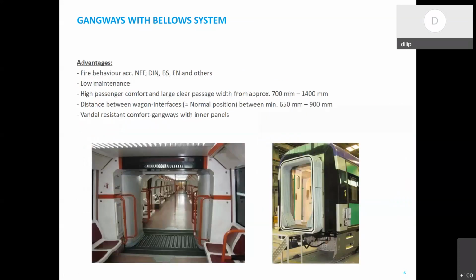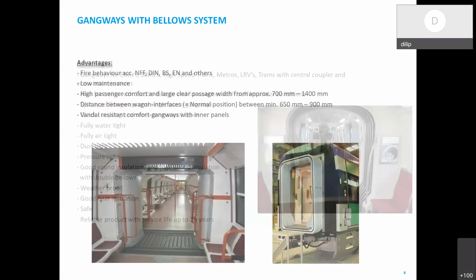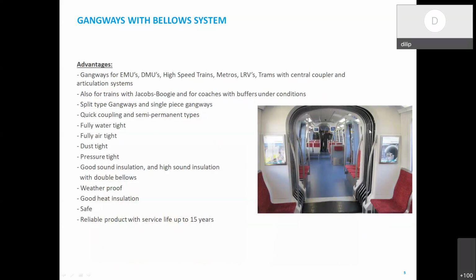So now coming to the other type of gangways, here if you see this flexible gangway, we are seeing these serrations, these bends. Here the metal linings are available, and we can see that it is hollow. So this is like a single layer. This is a single layer bellow gangway. So it will have only one outer element, basically the silicone rubber element.